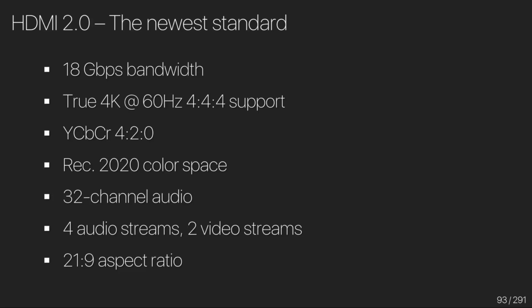Daniel is asking, isn't 444 the same as RGB? Thought 444 does not make use of YCbCr. You can have YCbCr 444 as well. So you can have RGB and YCbCr sampled at that same data level, and they should be equivalent in terms of quality. YCbCr typically gets used more with the 422, and if you were going to be sending 444, you're not going to save any bandwidth, so there's no benefit to using YCbCr. You could use RGB and get the same quality at the end.